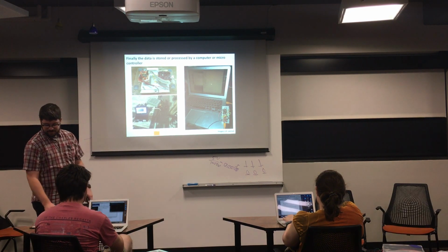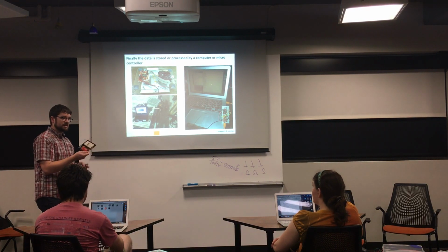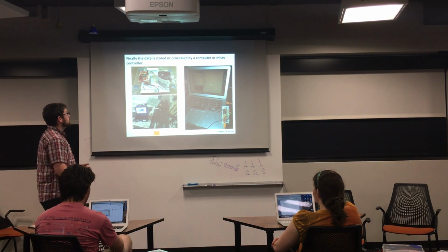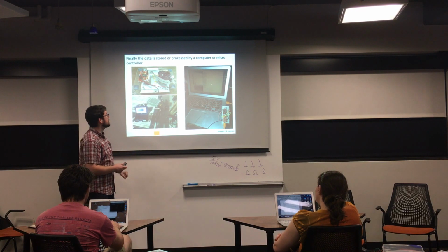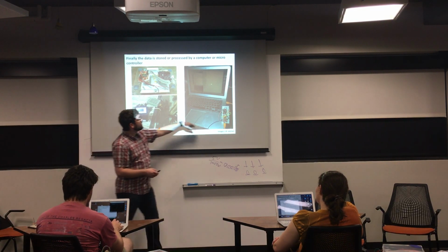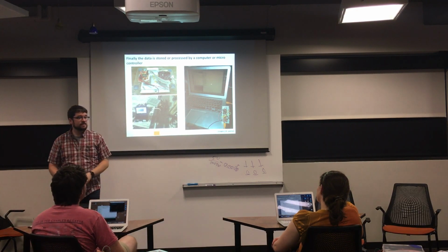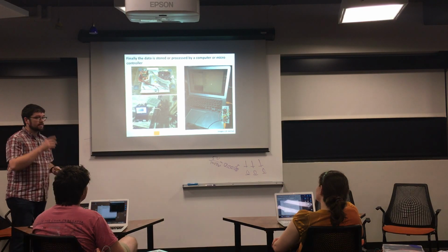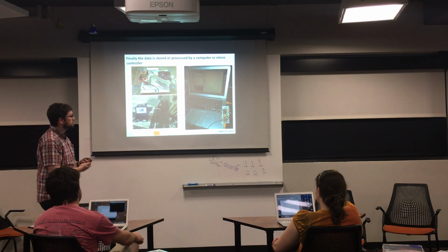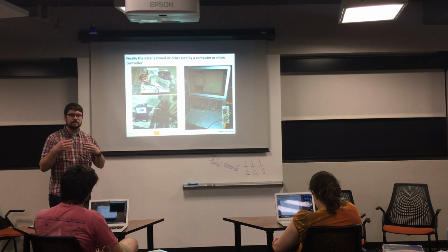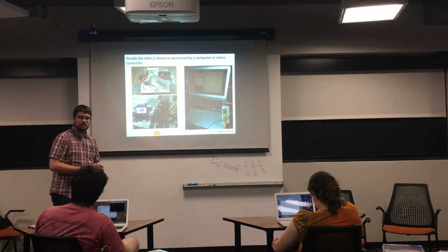And then once you've digitized that data, so let's say that you're just using this as the digitizer. Maybe you're not storing the data off to something from this, but you can. We generally connect it to a computer, or here you can see there's a logger that's directly connected to some kind of signal board. Here we've got a computer. This is a small version of the Arduino that you've got connected to my laptop, logging data. So you have to have some kind of data logging program. This can be that you're just sending text back and you're logging text to a plain text file. That's great for low throughput applications. You know, if you're collecting something at maybe a few hertz at the most for not a very long period of time.